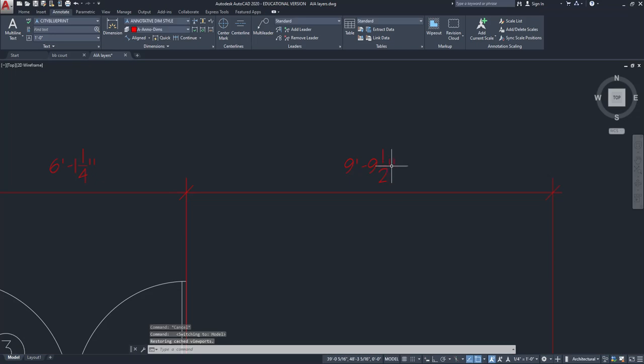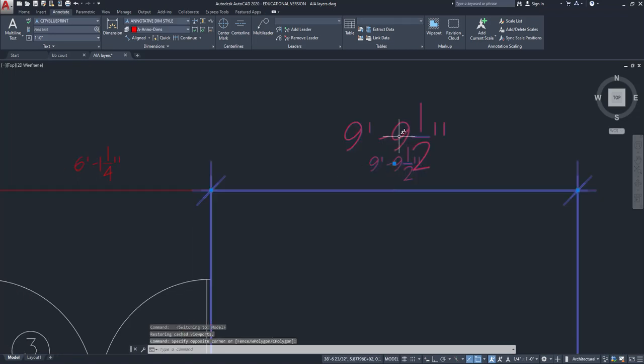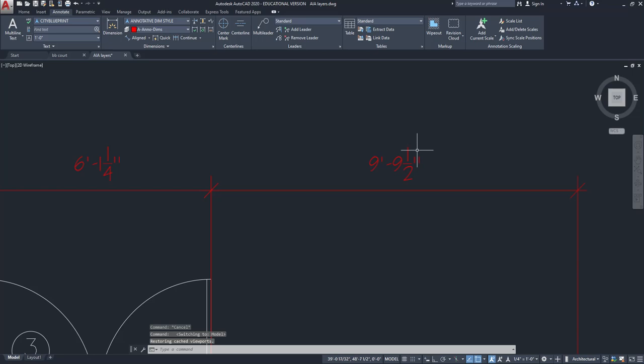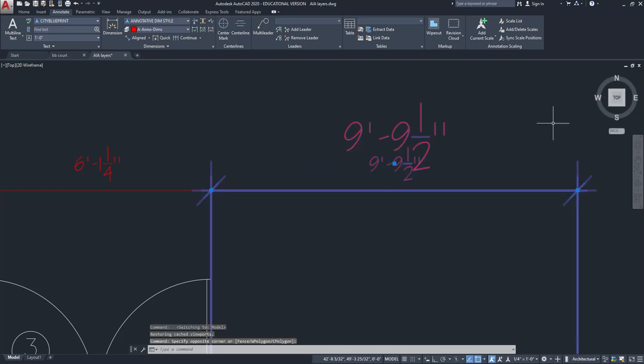Okay, so what that means is that my text for 1/8 of an inch has to be twice as tall as my text for 1/4 of an inch in order for it to look the same size on this piece of paper when it's printed. Okay, 1/8 inch, 1/4 inch, same size, which is what we love. But because AutoCAD zooms in differently to create those scales through the viewport, the text in model space has to be a different physical size in order for that sameness in Paperspace to happen.